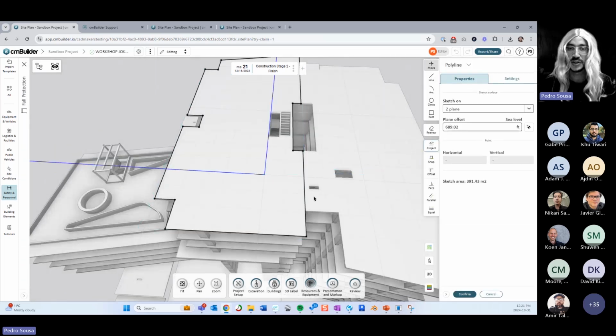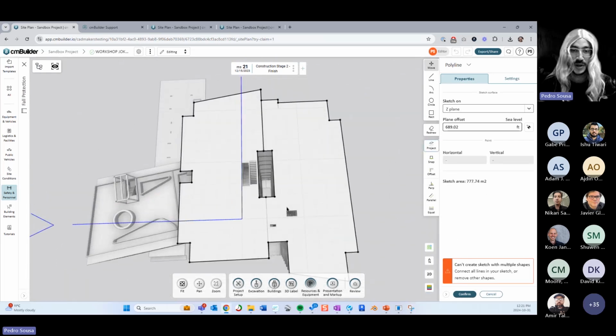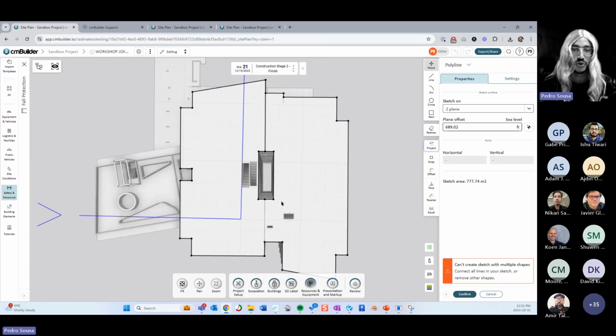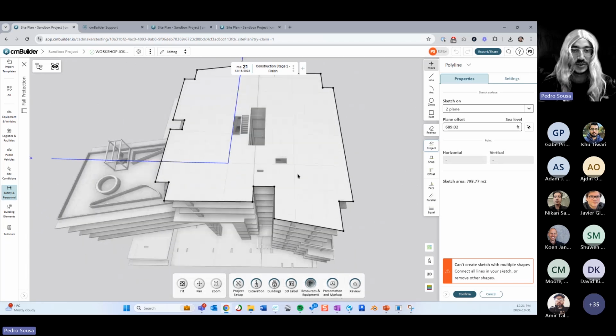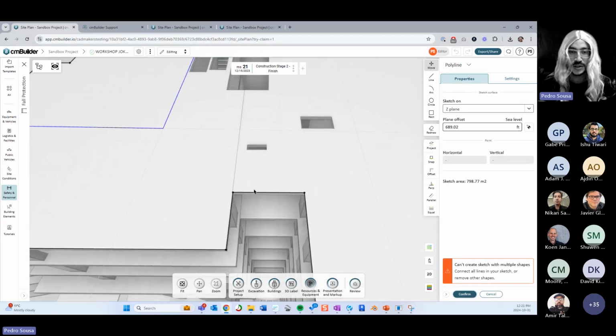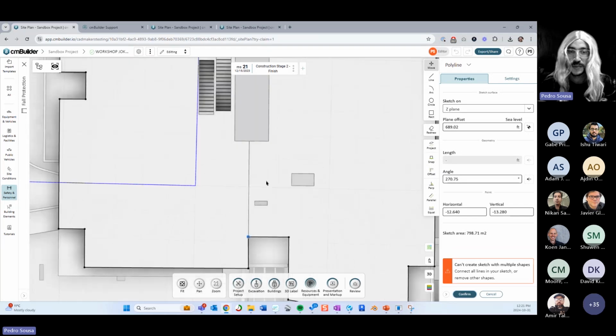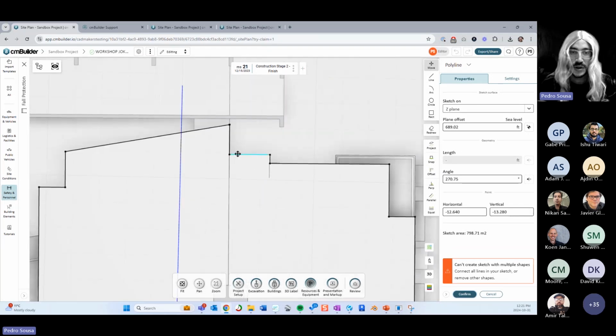I'm going to project the shape of both slabs. And I'm going to go ahead and delete these items over here in the middle. And because you can hold control and select several points and several lines at once, you can simply do something like this. And when you hit confirm, we still need to connect these parts.